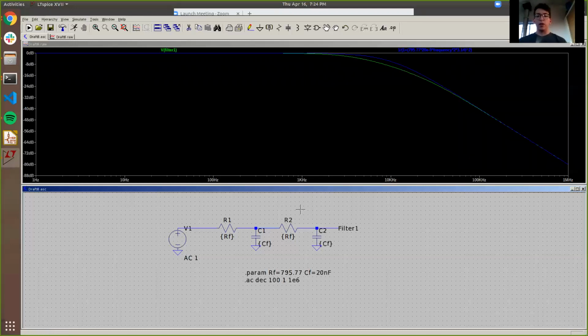So what is actually happening? Well, the current through this resistor is actually flowing into both of these capacitors, which is influencing the function that is describing the way the filter is working. In this case, it manifests itself as a cutoff frequency slightly before where you expected it.